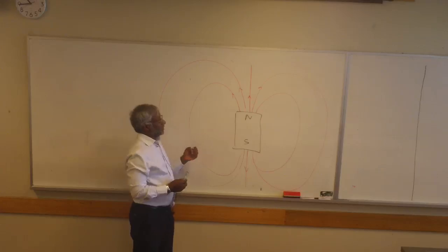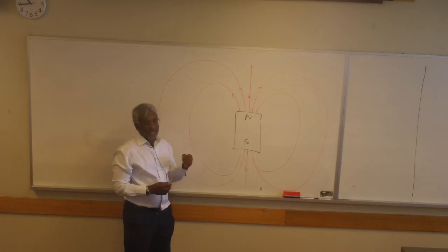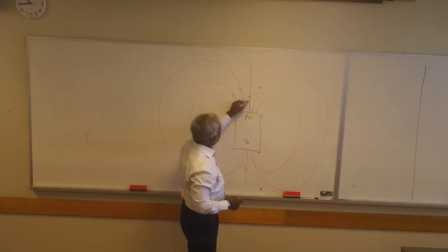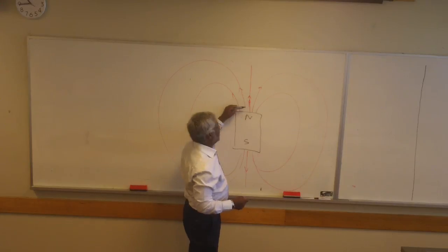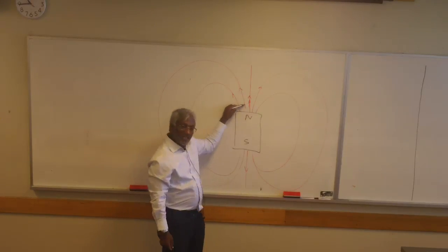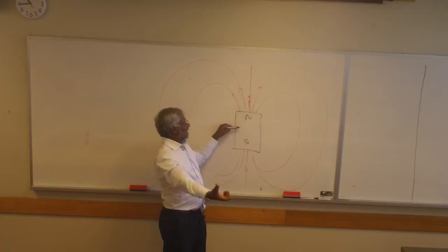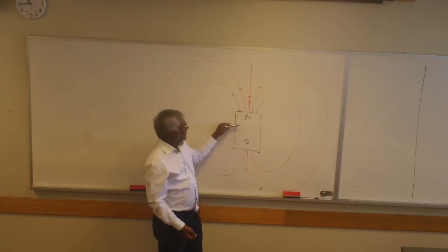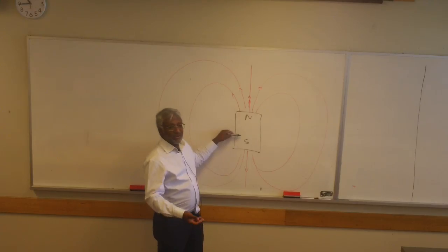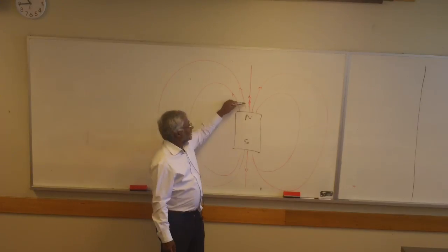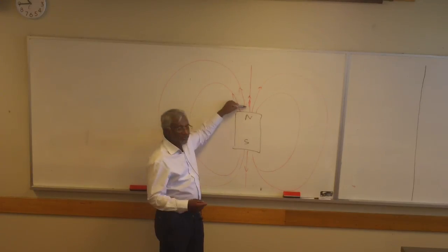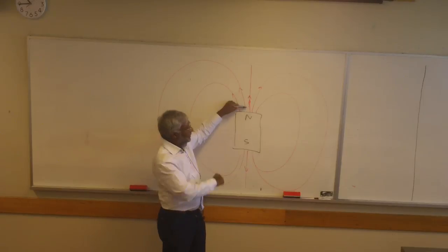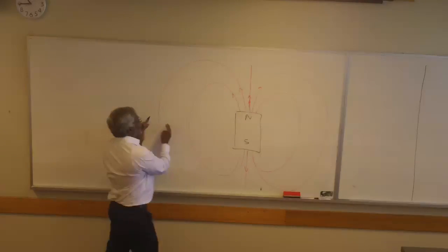And as I say, it is a field of numbers. The numbers would usually be the flux density. So you will have a high number here in space, representing the high flux density there. If you buy a magnet, which I've played with a few months ago, a neodymium magnet, the flux density close to it would be 0.5 Tesla in air. And then as you go away, it drops.